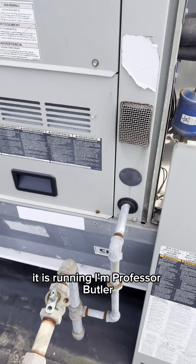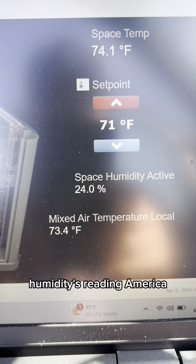it is running. So earlier I showed you this and I said foreshadowing, and it turns out the humidity sensor was not reading because this plug here was 1 pin over to the left. It actually needed to go 1 more pin to the right. That's why it's a bad idea to have this 2-pin plug on such a large pin out on the board. So that's why I said foreshadowing, and I lost the footage, so I'm doing this voiceover. There we go, humidity's reading.